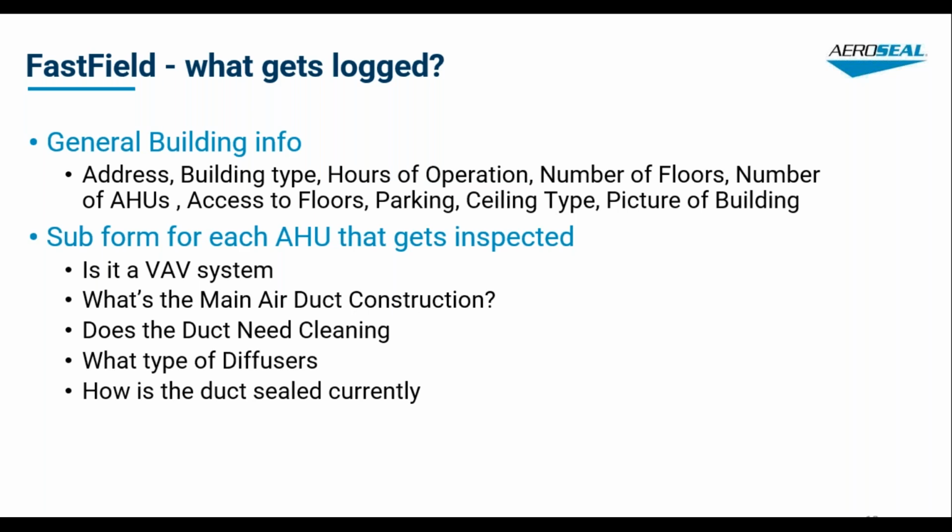So we look, and we get most of this information before we get on site. So we'll know if it's a VAV system, but we will identify while we're there that everything aligns. And then we look at the construction type. So the main run, how is it connected? Is it TDC? Is the duct welded? And then we also look for the duct cleaning. We'll take a peek inside the duct and see how dirty it is, get some photos, and then what type of diffusers, and then how well the duct is sealed. Does it have any duct seal on it at all? Does it have 50%? Does it have 70%?